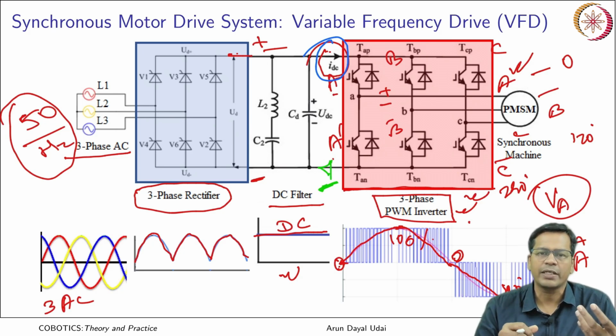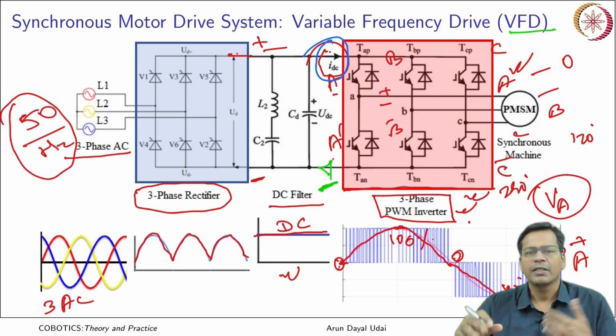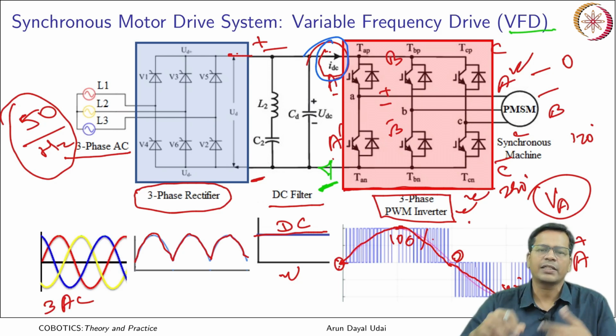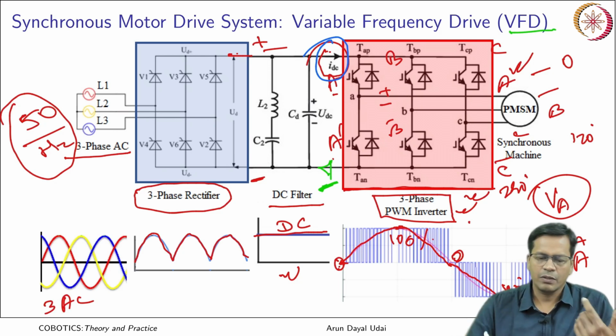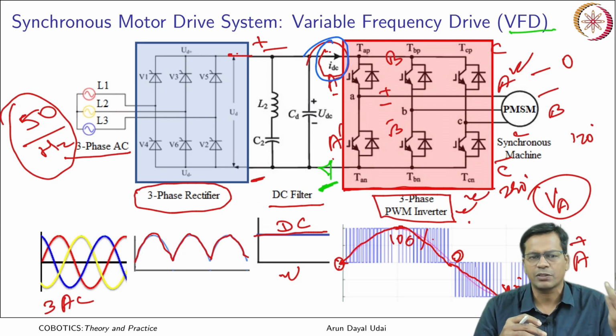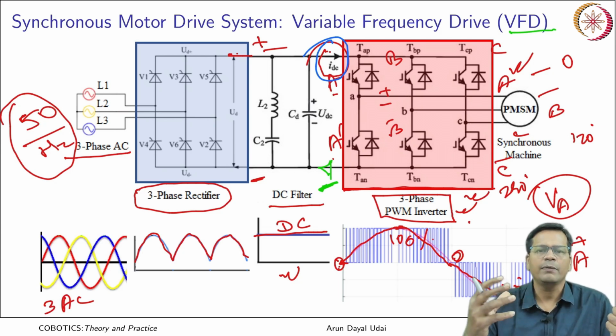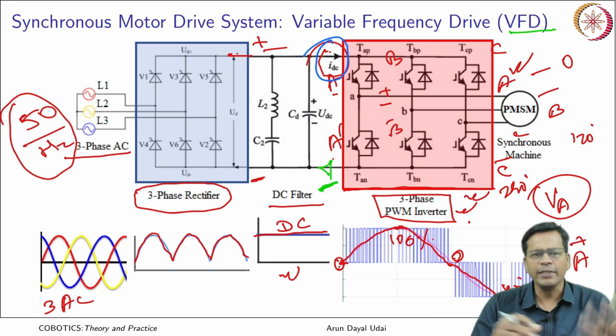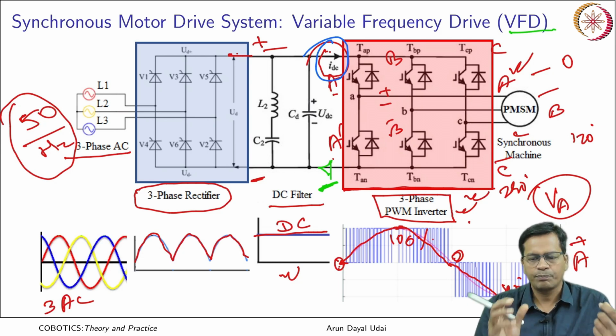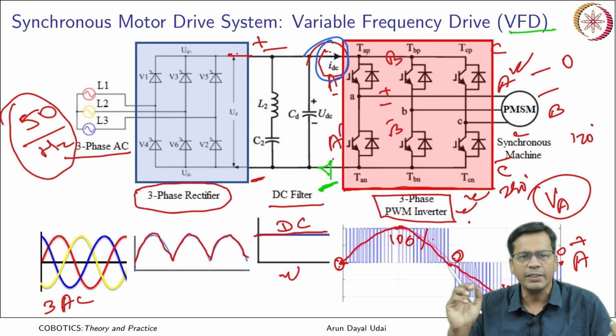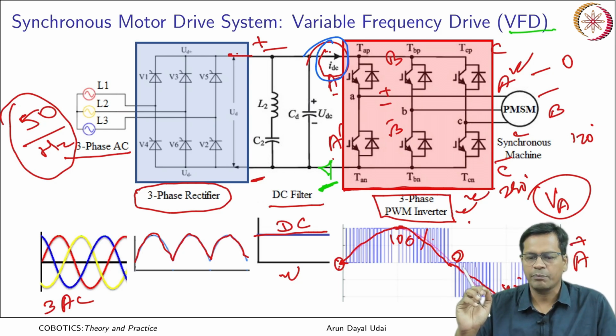Speed can be controlled by controlling the frequency of the variable frequency drive, and direction you can just reverse the direction of omega, that is the cyclic frequency of the 3-phase, that motor direction can be reversed. Okay. So, this is the way you can control the speed as well as torque and direction. If you have a position feedback, then you can have an external controller which can create a closed loop and can control the precise position of these kind of motors. Okay. So, this is how position, velocity and the torque of such motors can be controlled.